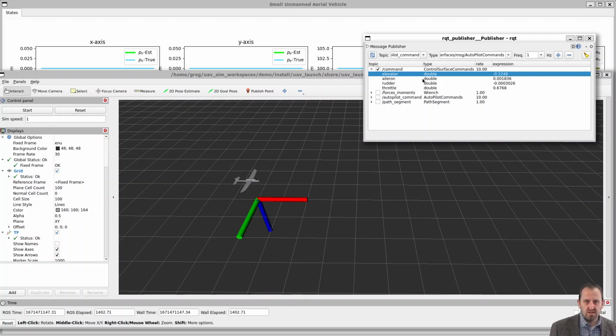And these commands, we can go between -1 and 1 for our throttle. We didn't talk about it, but that's going to be our propeller forces. And then we have our rudder, aileron, and elevator that we can command. Now I have it set here at some nominal values, and we'll talk about those nominal values next time in Chapter 5 when we discuss trim trajectories.